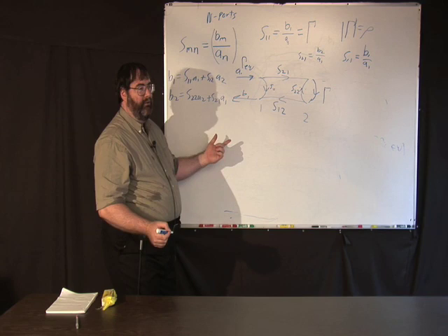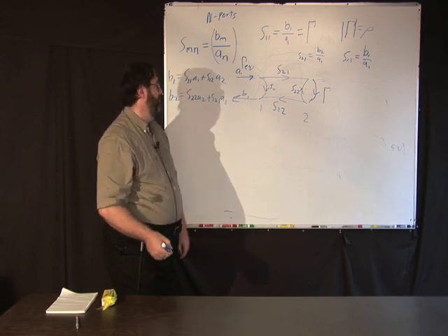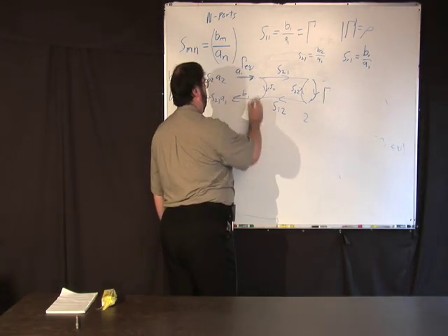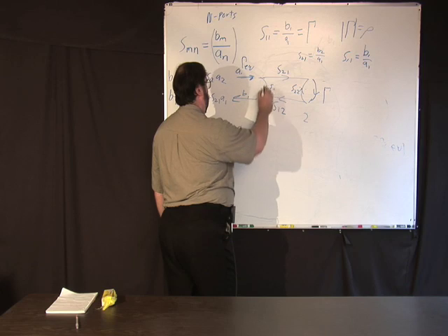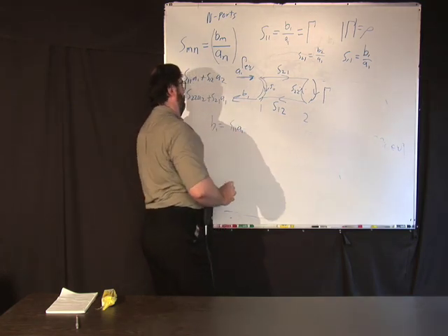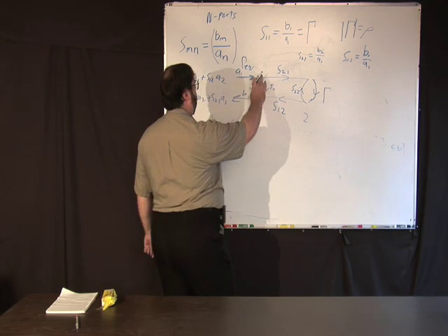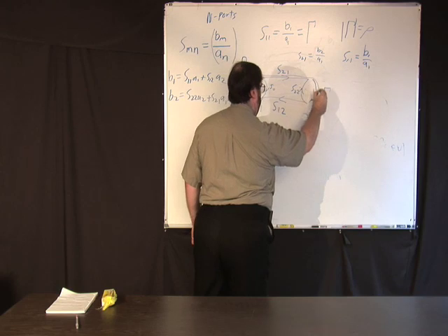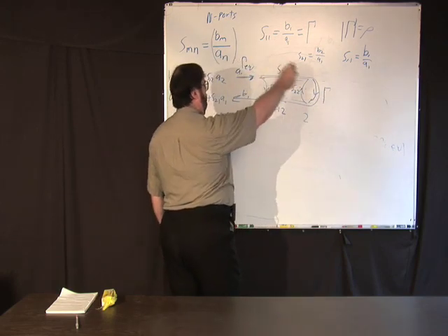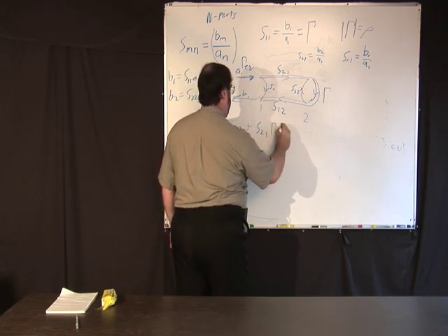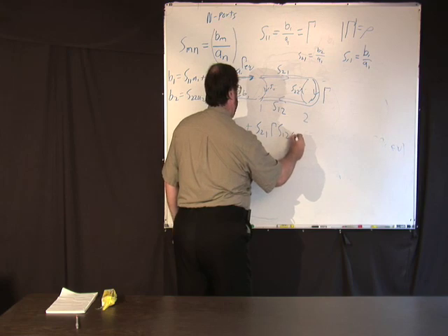Well, the way this works, and I'll show how these diagrams work, you could go through the matrix stuff, but let's do it this way. Something comes in, A1 times S11, and B1 gets that. Well, what else? You can follow the path of the signals through this. Here's a path through the device, this way, and this way. So you add all these up, so this is going to equal S21 gamma S12 A1.